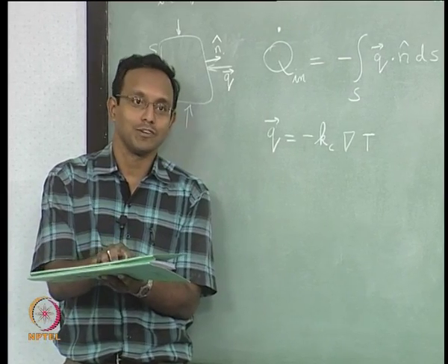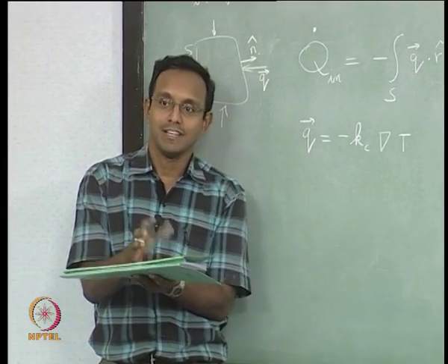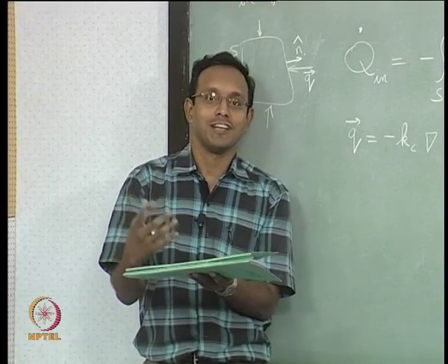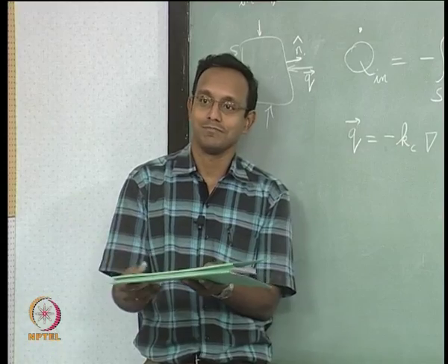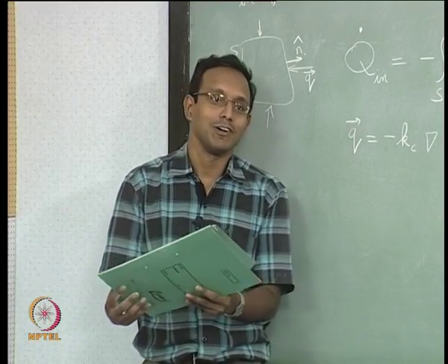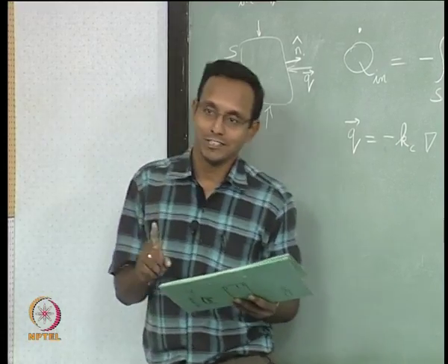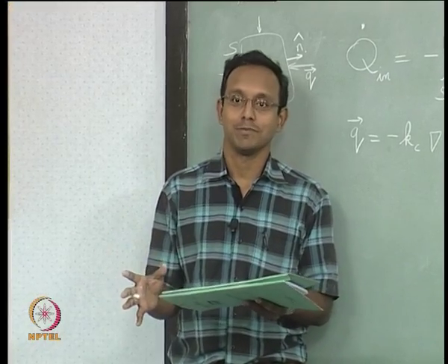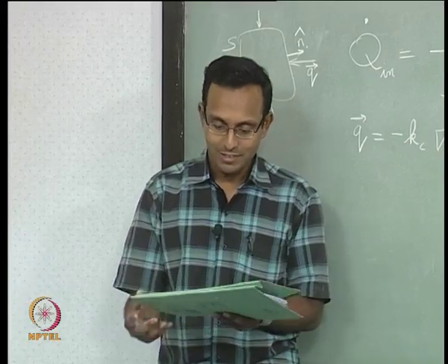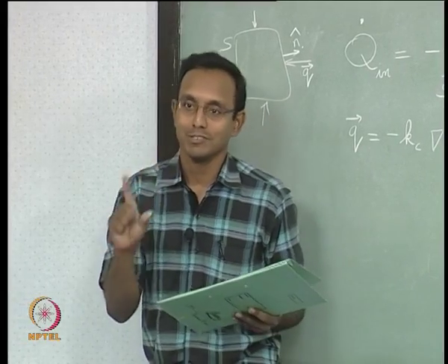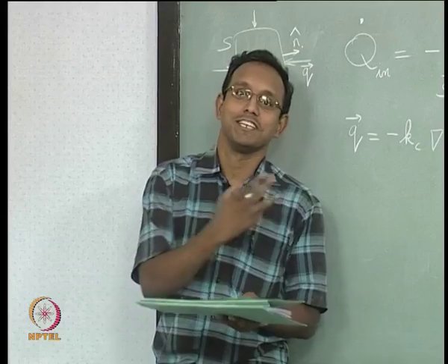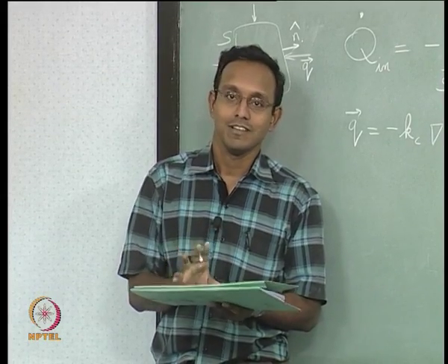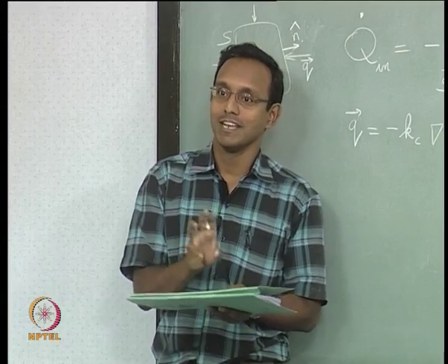Engineering-wise it is useful. They will just define one coefficient of heat convection and the problem can be solved faster. So, they have a separate thing called convection. Really it is just conduction with flow, that is what convection is, it is not anything special. So, we will not go into that, I am just going to say there is no separate convection term, that is why I wanted to introduce this. So, there is only a conduction term, there could be a radiation term.